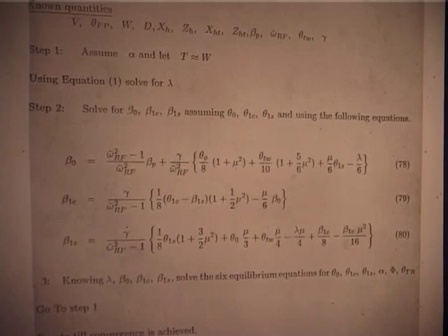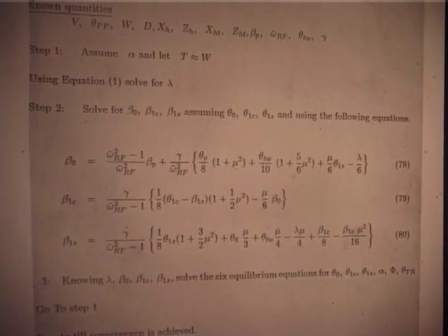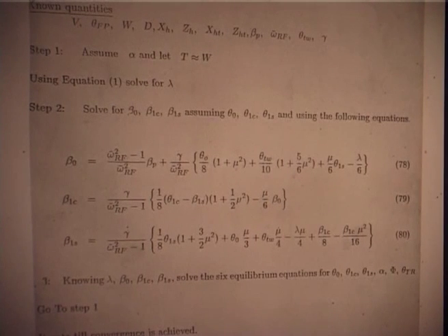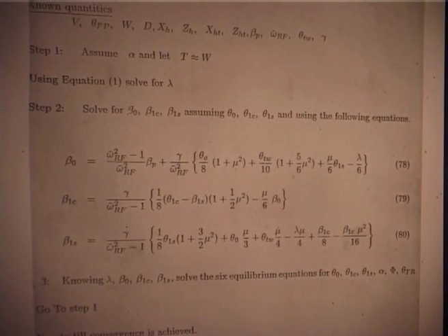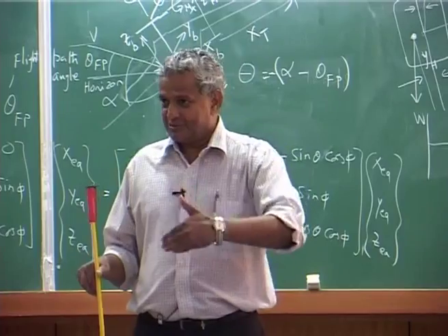equations are converged. Now, the convergence itself is a very interesting thing. You converge here, then whatever you come here you take it. But the key problem which is faced is you will find a thrust which is dimensional, it is like a 4000 kg helicopter or 5000, that is a very big number, whereas the side force they are all very small numbers. Then when you try to take equations, you will find that the big number will drive the result, but it may not converge properly. So, always all of them are non-dimensionalized such that they converge, they are all given equal importance, and then you get the converged solution.